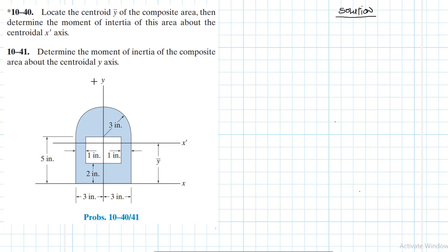If you remember, we've dealt with centroid and I've done some videos on centroid. And centroid is just a geometric center. We can think of it as a point where all the area is concentrated. And if the material is homogeneous, you expect the centroid to coincide with the center of mass. It can also coincide with the center of gravity within a uniform gravitational field.